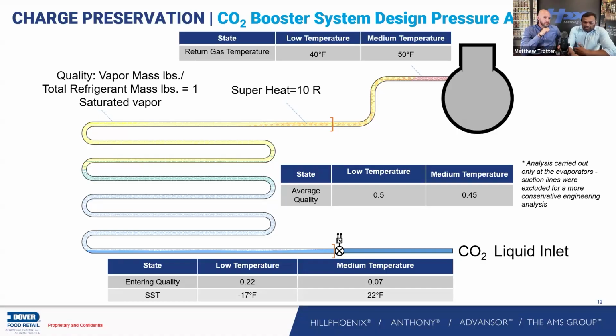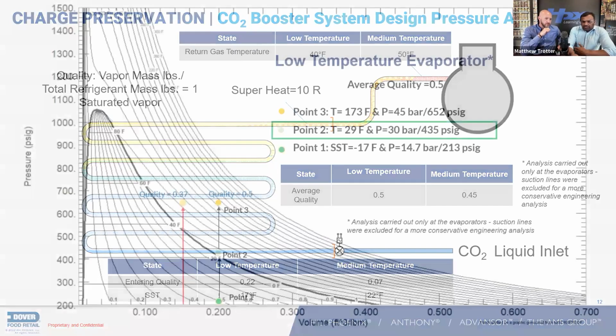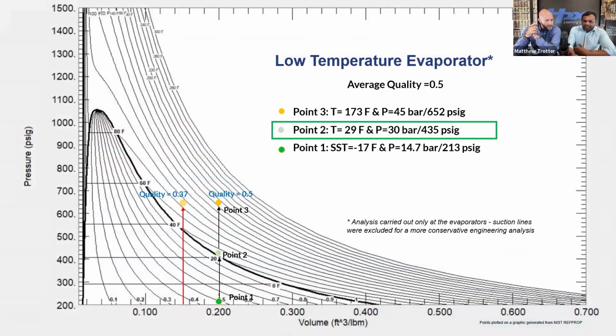So with this analysis, we also tested this in the lab. We took the pressure volume chart to see what happens after the power outage, right? Our main focus for this is to evaluate the liquid that's in the evaporator and how far we're going to actually expand and whether we're going to hit that point or not.